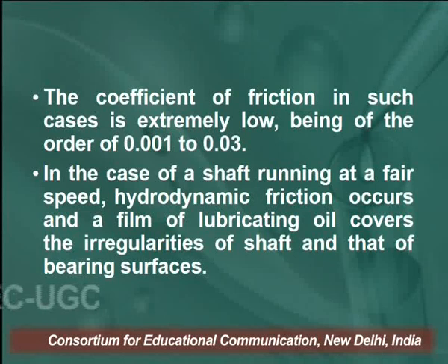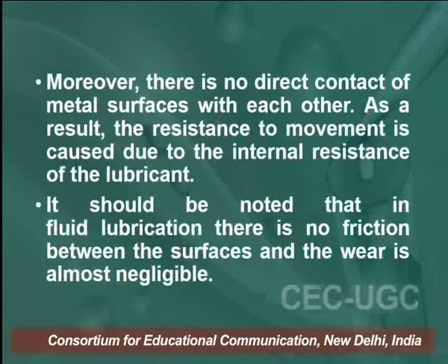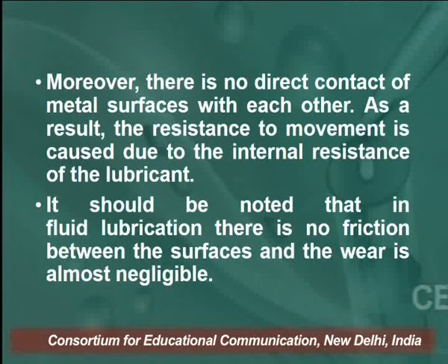In the case of a shaft running at a fair speed, hydrodynamic friction occurs and a film of lubricating oil covers the irregularities of the shaft and that of the bearing surfaces. Moreover, there is no direct contact of metal surfaces with each other.